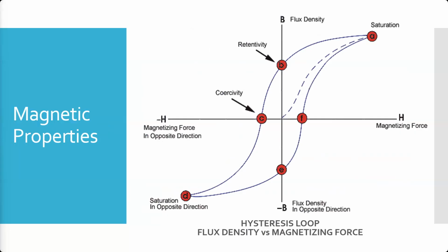And it's the same thing as that voltage starts to go positive again, it's going to pull us up to the coercive point in the movement from negative to positive field. You can see the H distance from origin to C and origin to F are about the same. It takes the same amount of current going the opposite direction to get there. And then as it continues to rise, we'll start the cycle all over and reach that positive saturation.